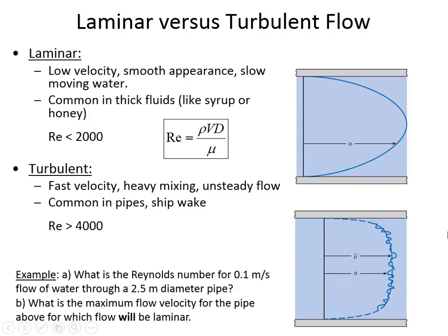And so here inside of the pipe, since the edge of the pipe is stationary, the water that's touching the edge of the pipe right at the boundary layer also has a velocity of 0. But then there's a layer of water above that, and that layer of water is slipping a little bit faster than the layer below it. The layer below it is 0. And so there's a very orderly transition and an increase in velocity until when you're the furthest away from those flow resistance surfaces, from the pipe walls, the velocity is maximized. And there's a parabolic distribution for the velocity profile.